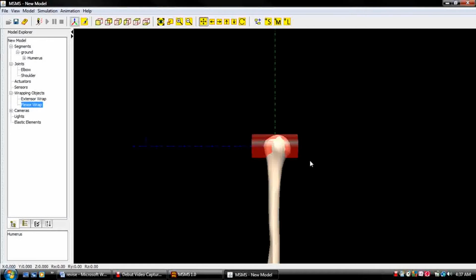And we're going to hold the shift button and the Y button until it is negative 0.12 meters down the Y axis from the origin. So I'm going to do that. Make sure first that you activate the 3D window and then you select the object that you want and then shift Y. And now it's going down.